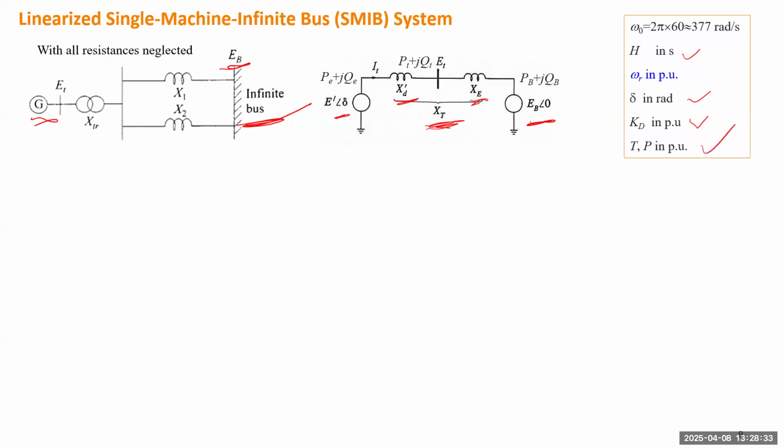The meaning is that for a 1% frequency change, it will cause a 1% power or torque change. Torque and power will be in per unit, which means that for either mechanical power or electric power, the mechanical torque and electric torque will take the same value in per unit. The special one is that we want to keep the rotor speed in per unit because we don't want to see omega 0. Omega 0 is the actual synchronous frequency. I want to make the equation simpler, and here we specifically require omega r in per unit.